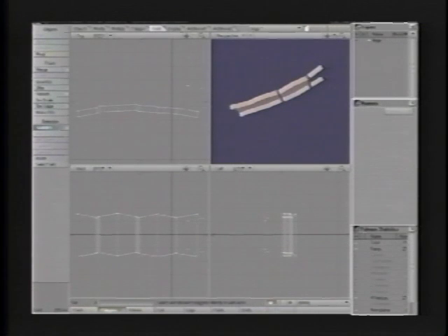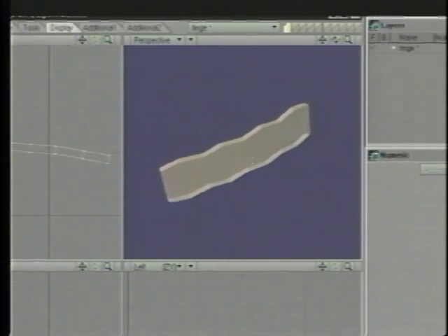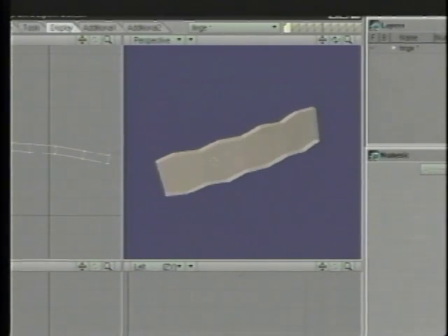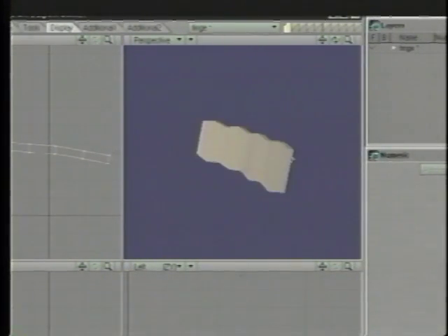So we can deselect those, or select those rather, and just kill them. All right. And then there's one here. Kill that, because I don't need that. That was an internal polygon that's no longer going to be necessary. And I continue to work on that until I have this whole thing stitched together. And then it'll end up looking like this. So you can see all these stitched together. We have one seamless, continuous mesh.